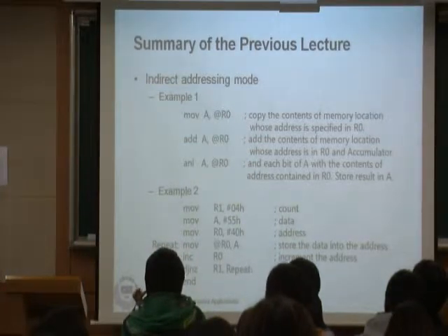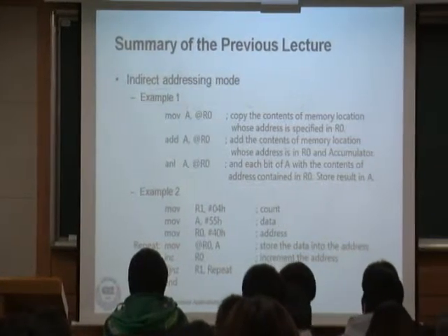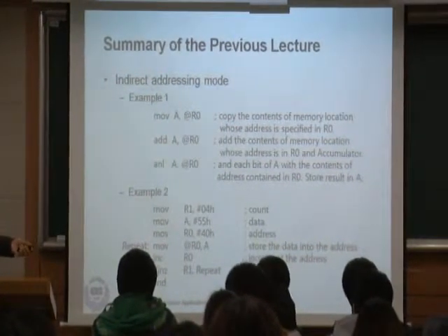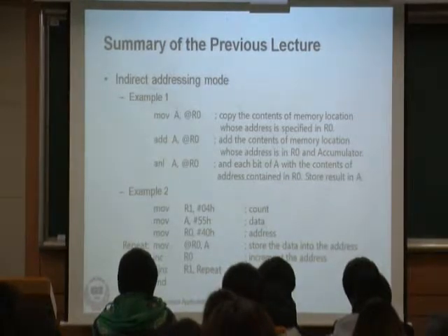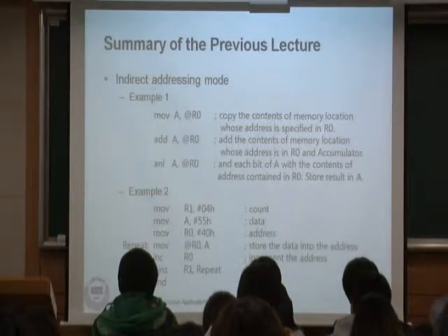What is the best way to do it? Use your emulator or simulator in your PC. Write down your assembly code and just run it line by line and see what happened to the register values. That's the best way to learn this. And possibly